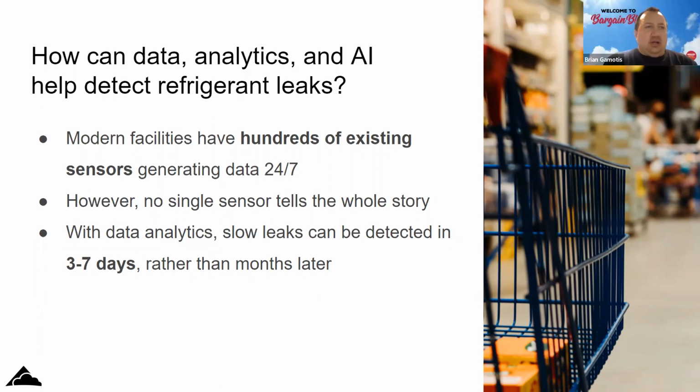We still have a lot of stores that have single systems, so we don't necessarily have the ability to track the refrigerant levels in the individual singles. And the data analytics side is a relatively new concept of how to look at refrigerant leak detection. So we're just starting to move in that direction, looking at more than just a liquid level switch or a liquid level analog gauge.